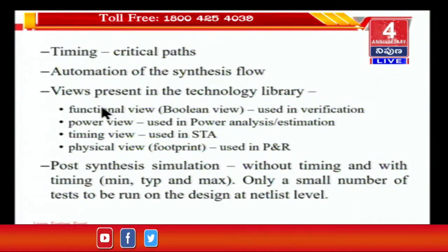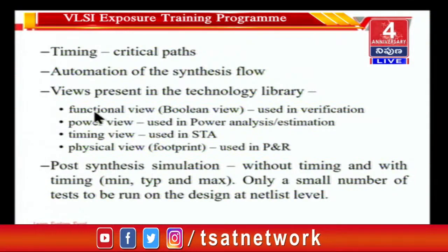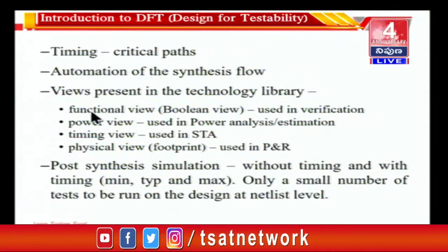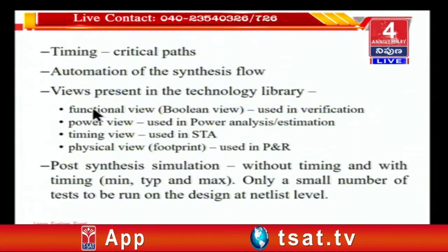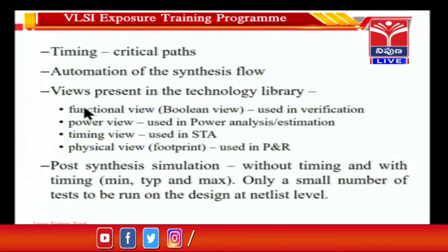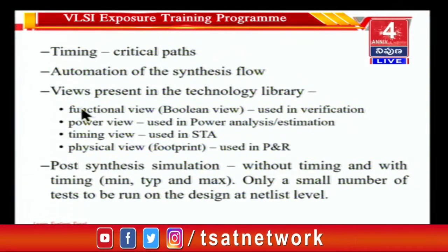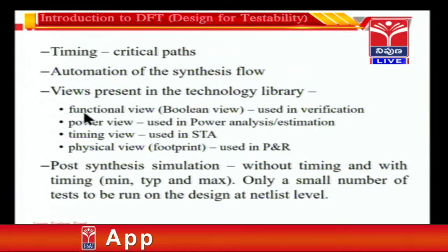So this Boolean view is used to find out whether the gate level functionality is meeting the RTL level functionality or not. The RTL level functionality has been verified through the use of a test bench by applying the inputs through the test bench. Therefore, assuming that functionality has been completely verified, we are now trying to see whether the gate level simulation also meets certain requirements or not.